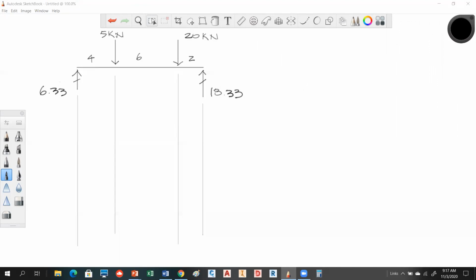Okay. All right, so this is my free body up here. And remember, I call these critical lines. There's critical lines happening along your point values, okay? So underneath this, we're going to start to construct the shear diagram. This is where a straight edge and a scale is really nice. I'm going to put my shear right here. So this is my shear, and that line represents a point of zero shear. Above it is positive shear. Below that line is negative shear. Is everybody with me?